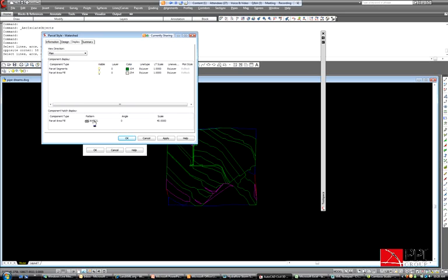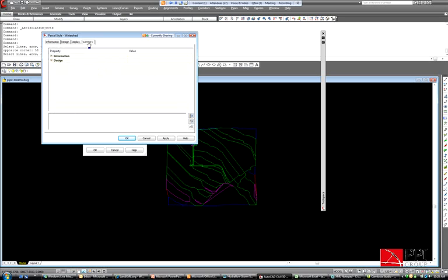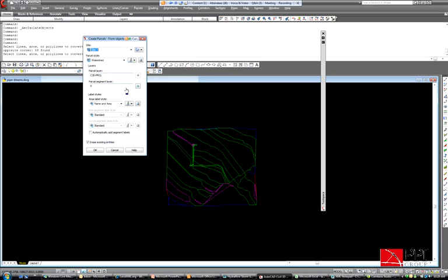And all it is, I've got an ANSI fill on there. You can do whatever fill you'd want. And the name, this name is what's going to show up in a lot label style. This is called lot, and then the number 1 or whatever it is. But in the watershed parcel label style that I've created, it's called watershed. And so I'm going to say OK to that, and everything else looks pretty decent other than the